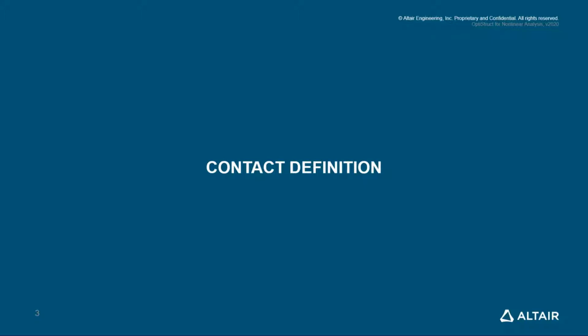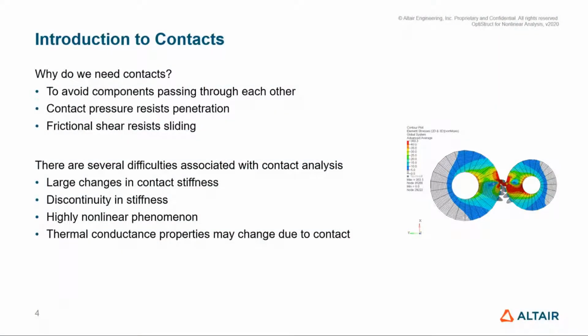And most of the time when there is a non-convergence issue or some difficulty in convergence, it is mainly due to contact, especially if you have a lot of contact in your model and if it involves large displacement. So normally those are the things that will cause you some debugging time, right?